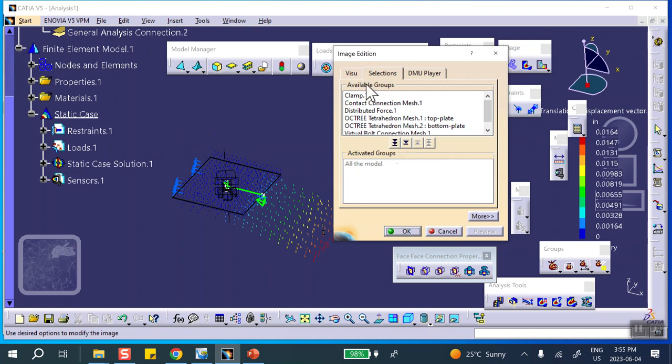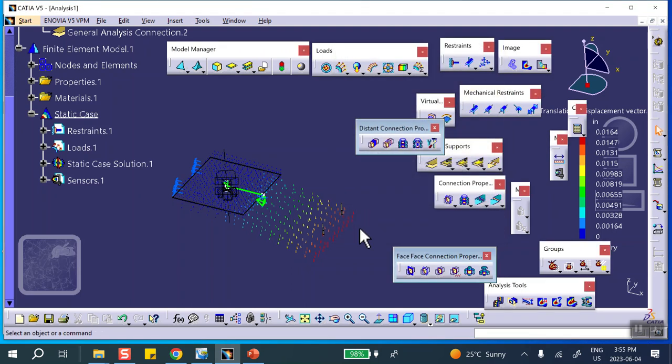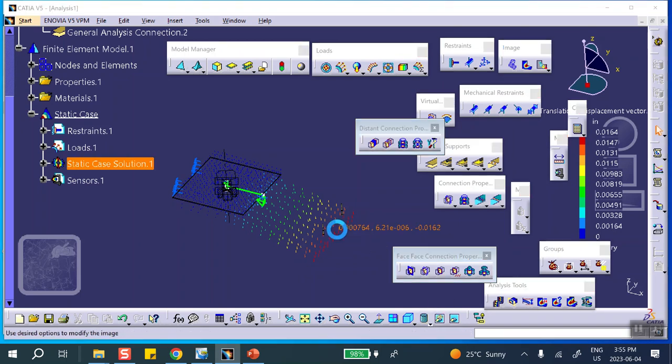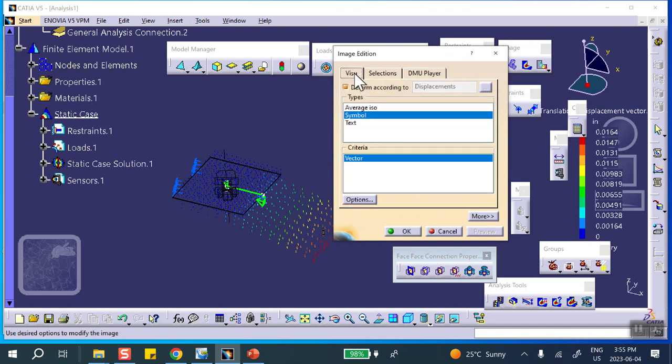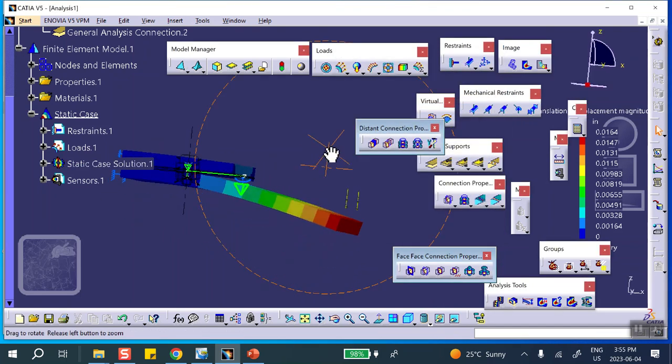Now, we're not doing any mesh convergence study here. Therefore, these are just colors and numbers. We don't have any confidence in them. And one really has to perform a mesh convergence study to find out what's going on. Okay, no bolt.